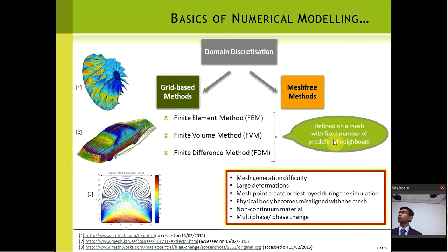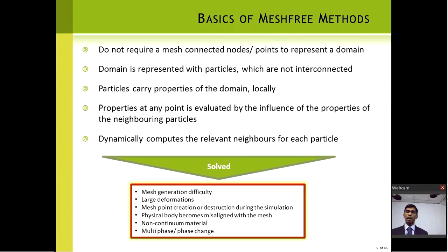So to solve these things, people thought of a different paradigm, which is the mesh-free method. Can't we do things without grids or mesh? That is called mesh-free, or grid-free, methods. When it comes to the basics of mesh-free methods, these are the key points. They do not involve a so-called mesh, so that is mesh-free. And frequently these methods represent a problem using particles. The particles carry properties like pressure, velocity, acceleration. The particles move. If a fluid moves, particles move. I'll show you some examples in time to come.